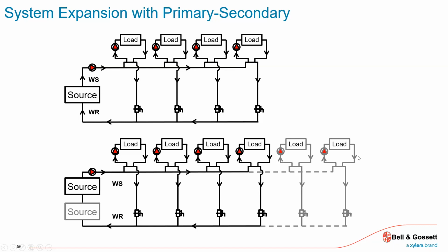or this flow rate, if this piping is sized, sometimes what they'll sit back and say is, hey, if I increase the temperature here, I can take a bigger delta T. I can now support these additional two buildings or crossovers to support the new load. It's a clean way of adding capacity.